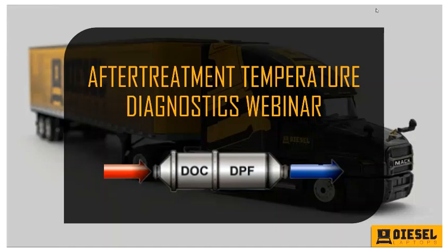So in this section of the webinar, the temperature diagnostics, we're focusing on the regeneration side of the system. 2007 to 2009 vehicles all have this. And then 2010 plus, they continue to use this system, but they add SCR. So my goal is to make sure you understand how the regeneration side of the system works. When we run regenerations, what are the temperatures telling us, so we can troubleshoot these vehicles much quicker and easier.